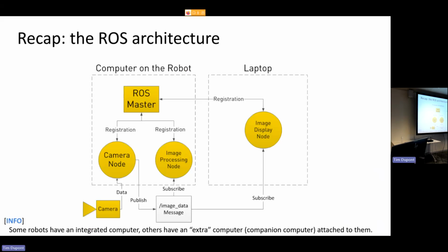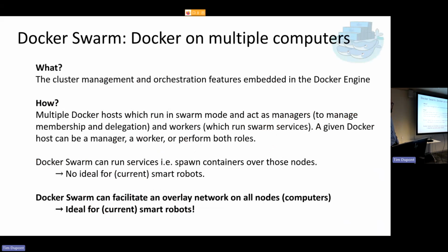And if it's running in production and there's an issue and you want to see inside the robot, you can just connect your laptop to the network and start a ROS node for the visualization on your laptop and immediately inspect the complete robot. So you don't have to be in the vicinity of the robot, just in the network. That's the power of ROS. It just works out of the box. It's not really a hassle.